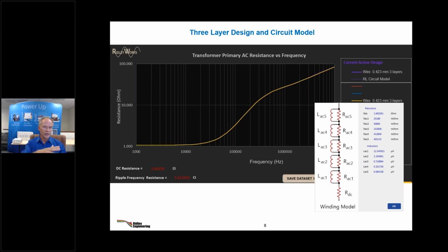We're doing this in the frequency domain now, but now you can take that frequency domain circuit and simulate it. So we're going to ask LTspice to do the hard work of hitting this with the actual converter currents and then figuring out where the currents are going and what kind of dissipation you're seeing in each of the resistors. Mathematically, by hand, it's a nightmare.